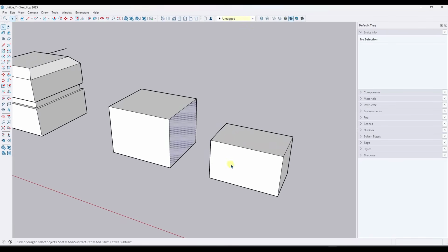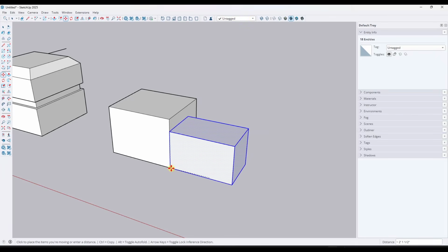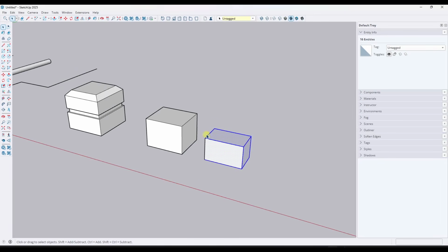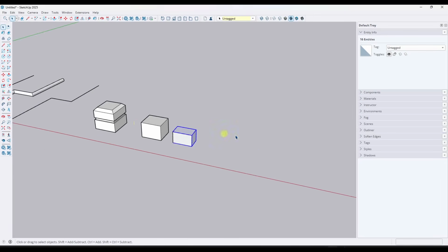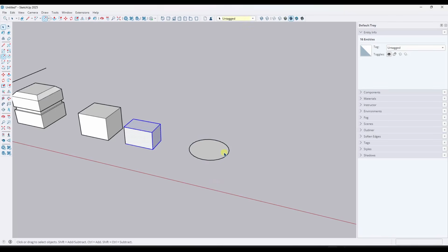So notice how if I click on these boxes, this is going to allow me to select the individual parts and pieces of the boxes. Well, one of the things that you might have noticed is if I activate the Move tool, so I pre-select this geometry, tap the M key, and move it over here, one thing you might notice is that geometry actually fuses together. So if you push raw geometry together like this, that geometry is going to merge and it's going to affect the way that that geometry interacts, which can be really interesting.